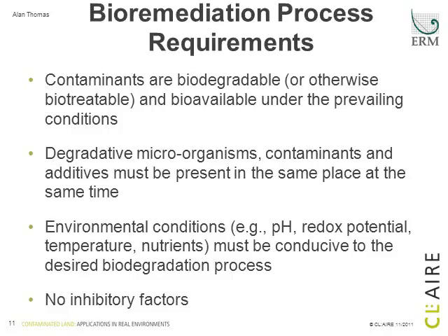So the requirements for bioremediation processes are really that, again, the contaminants are biodegradable or biotreatable, and importantly bioavailable under the prevailing conditions. Biodegradation is a process that occurs in the aqueous phase, so we need our contaminants in the aqueous phase for bioremediation to occur. So they must be dissolving or be capable of being actively dissolved for bioremediation to really work properly.